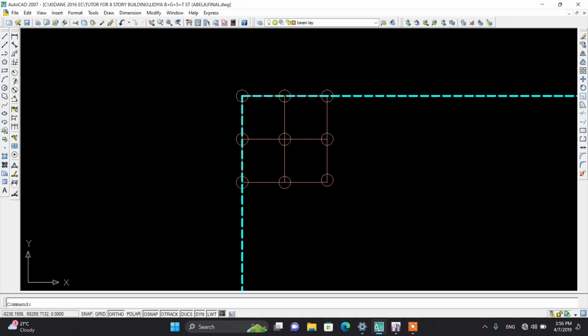So if you multiply these 8 nodes by 6 degrees of freedom, that is 3 rotations in XYZ and 3 translations in XYZ, you get 48. That is 6 by 8, 48. That is 48 equations used for analysis.